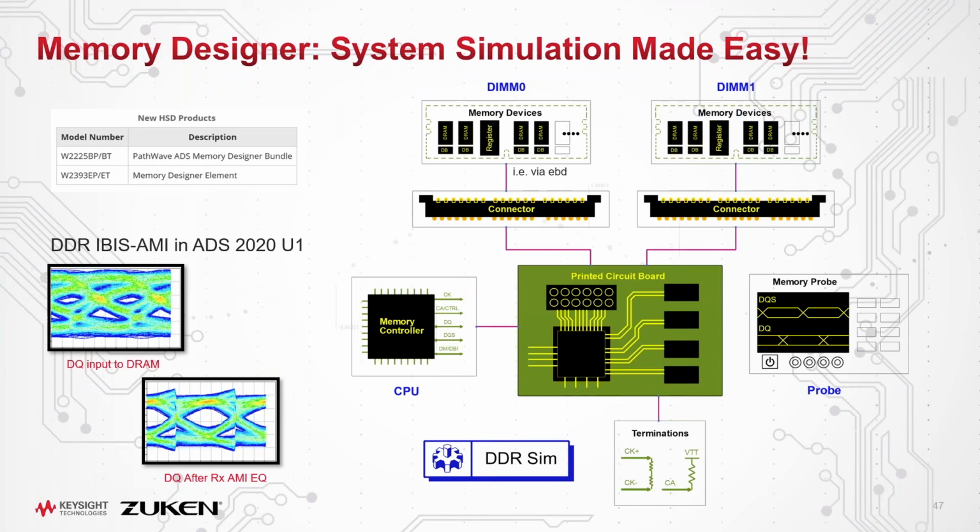Something which I haven't mentioned up until this point, though, is how are we going to handle the equalization models. So this is very interesting, and in fact, we've got a whole other webinar that will be coming up soon to discuss how IBIS AMI is being used in bit-by-bit bus simulation for DDR5. But at least I can tell you today that in ADS 2020 Update 1, which is shipping later in November, we will be able to use the IBIS AMI models for DDR5.